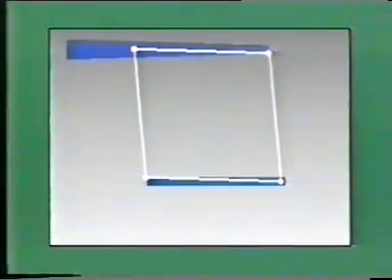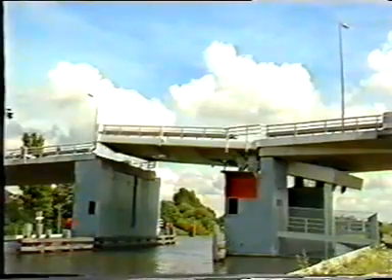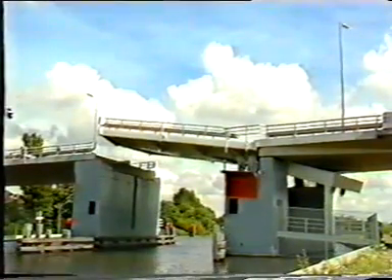A Scherzer bridge is in fact a bascule bridge with overhead counterweight, in which the balance frame is integrated in the tail of the bridge. The four hinges are replaced by one center of rotation. The section behind the point of rotation, the tail, moves in a pit or in free space.